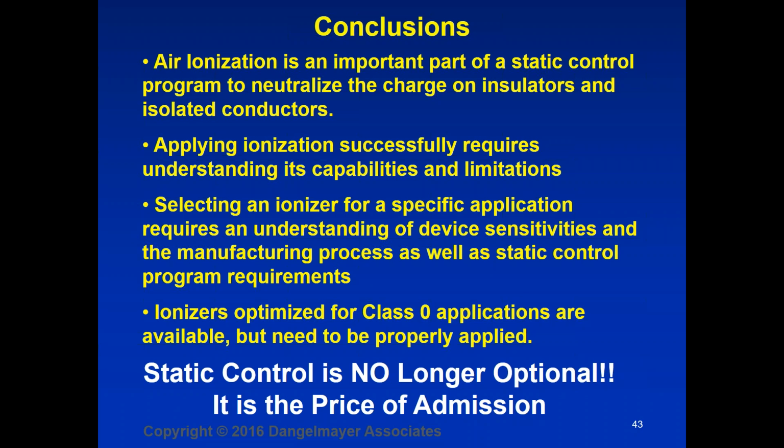We need to engineer the use of the ionization for the specific application, as not all ionizers will work in all applications. We need to know that ionizers that are optimized for Class 0 applications are available, but they also need to be properly applied to be effective. You can have the most sensitive ionizer, the most well-balanced ionizer in the world, but if it's not facing the product it needs to protect, it's completely useless. We need to properly apply them.